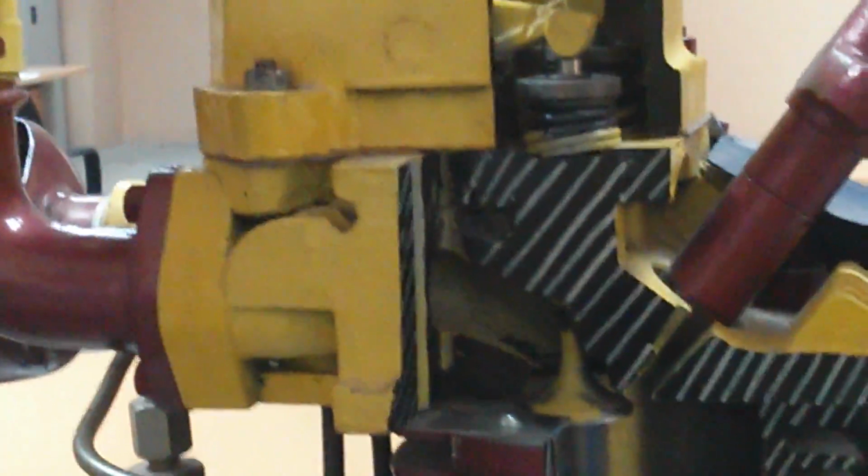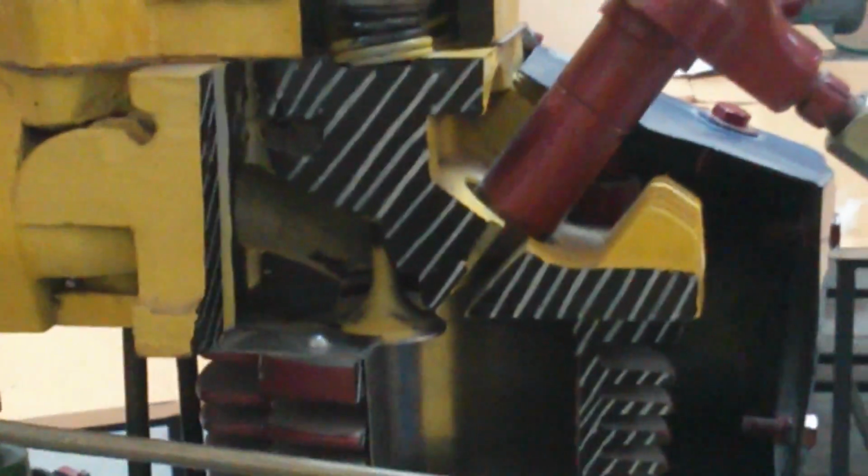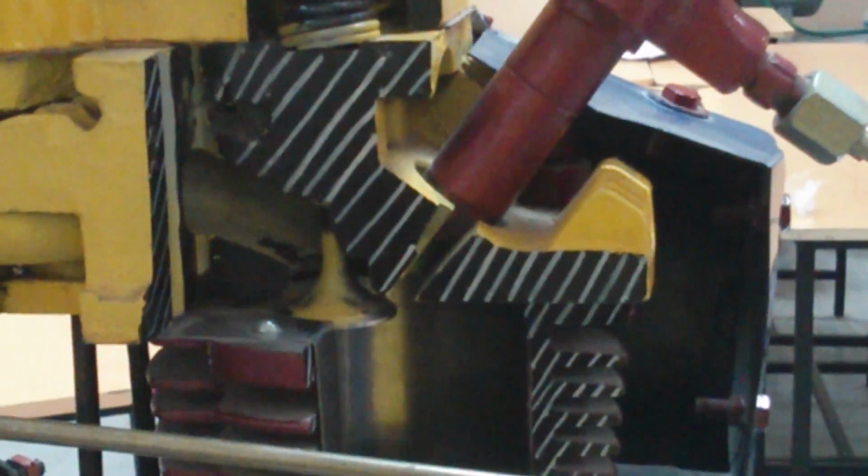So first you need to find out the inlet valve opening. Basically these valves are opened with the help of a cam and rocker arm mechanism. This is the camshaft, right? On the camshaft there are cams. I have a cam for the inlet valve and a cam for the exhaust valve, and there is a separate cam for opening and closing the fuel injection nozzles, right? As the crankshaft is rotated, the camshaft is also rotated.